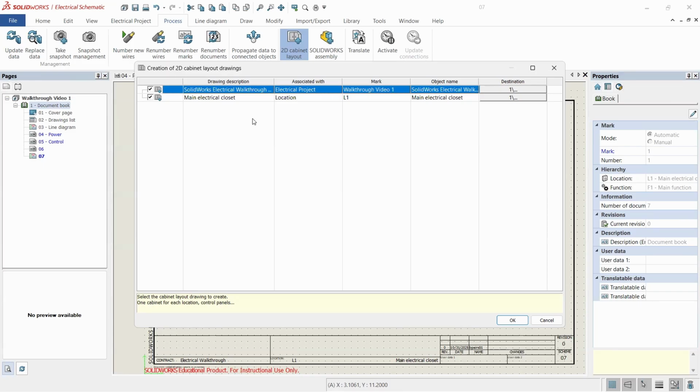In the case of cabinet layouts, it's also important because I'm only allowed one layout per location. And that's a problem sometimes. For instance, if I want to do a layout for buttons that I have to cut holes in the door of the cabinet for, and then the back plane, I only get one layout, so the back plane's the important part, but then I don't have anything I can do the whole layout for the buttons with. So in that case, I might create a location that says main cabinet back plane, main cabinet box, and separate the two so that I can get two different layouts.